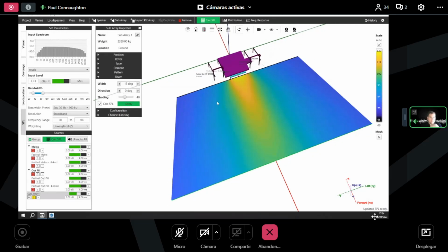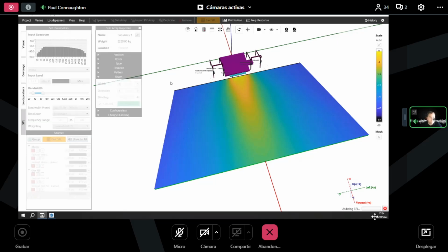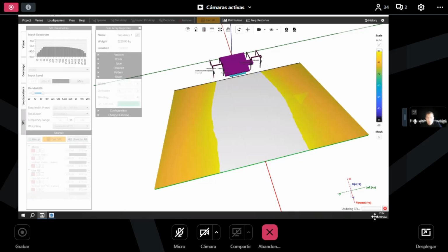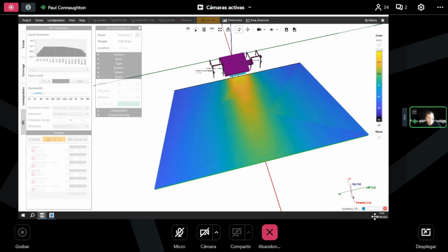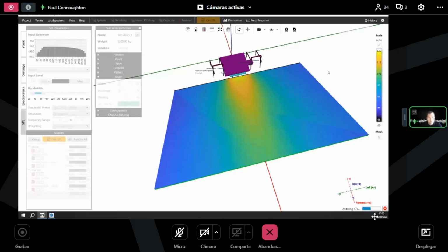Here we are. So that's a 15 degree beam. Okay, let's try a 30 degree beam and see if we can get a better result. Now, click apply. I'm going to go through and have a little play. Everyone, right now, just have a little play with width, incrementing width in 15 degree increments, if you will, all the way up to, for example, 90 degrees. So if we do 15 degree increments all the way up to 90, you get an idea of how this section works and how it maps, and it gives you a bit of time to play.